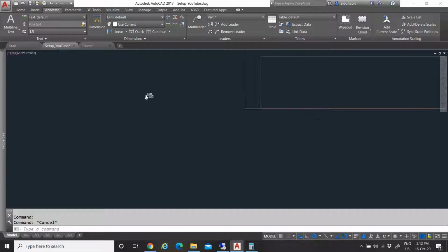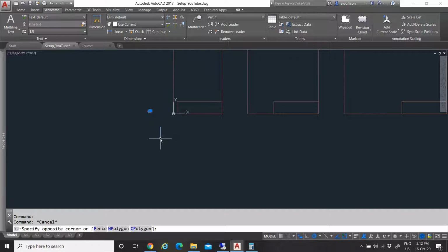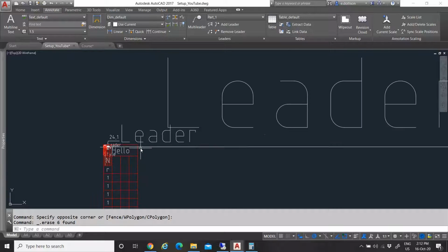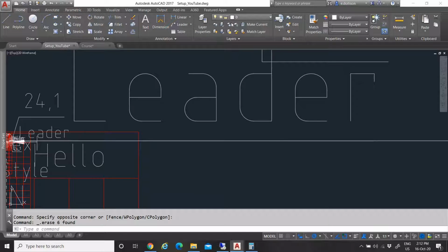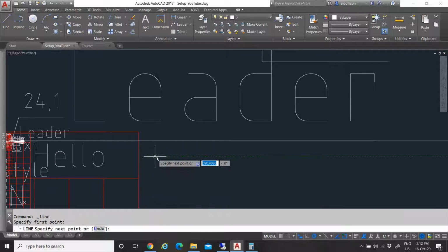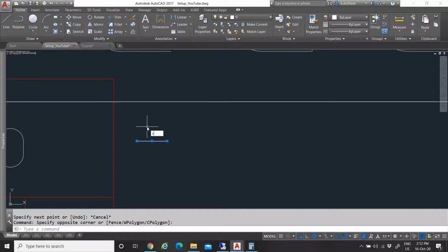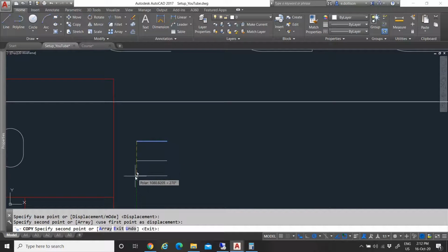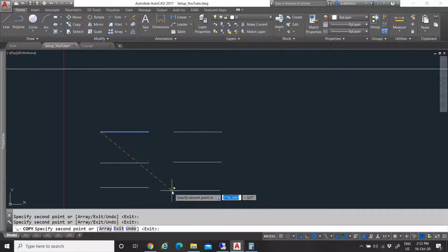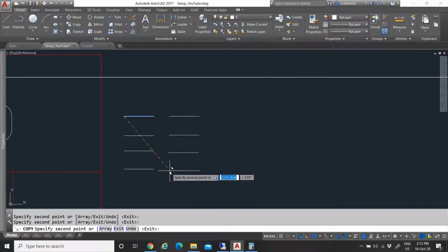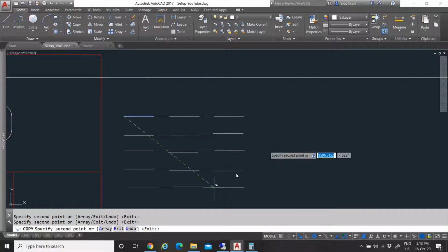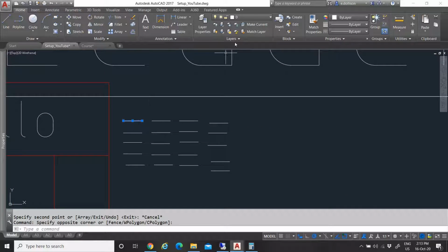Now one more last thing, guys, is your layers. That will also be purged if you don't add it to your drawing. So let me copy paste this a couple times. Or what you can do is just, no, let's just do it with lines. It really doesn't matter how many lines, how big the lines are or where they are, as long as you add them.